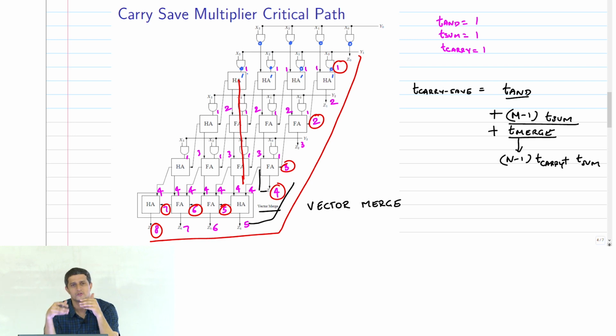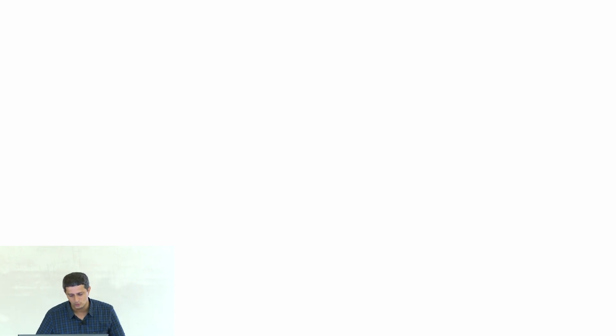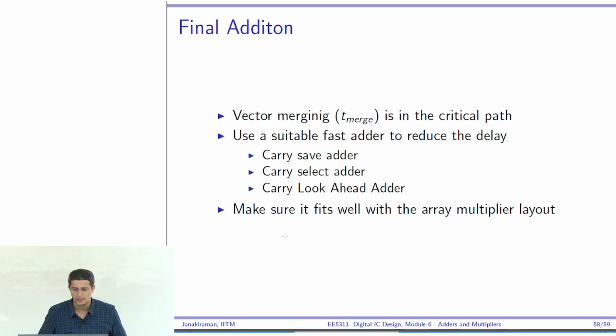Okay? You have to just figure out how to put this. You put NANDs, then you'll have to have a full adder which gives the complement of sum and carry, then propagate it appropriately. Okay? With that, we have really covered the key aspects of multipliers, both signed and unsigned. As I told you, I don't have time, so I will not do it.